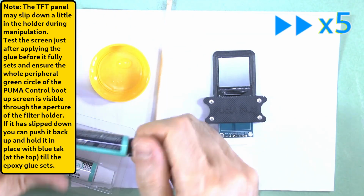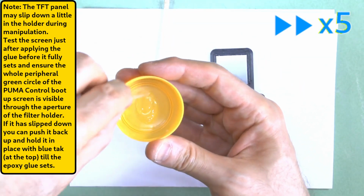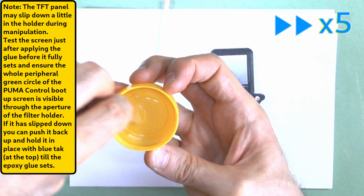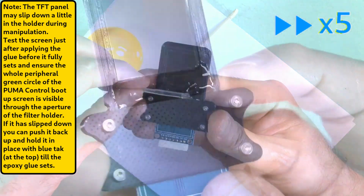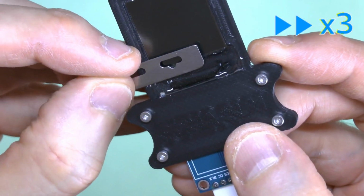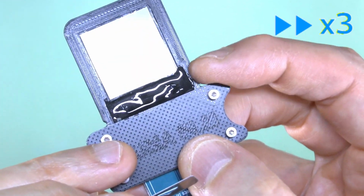Now that it is fully assembled and working, disconnect the power and further strengthen the fragile thin glass connector by putting a second wave of epoxy in the recess around and over the thin glass extension to strengthen it. This time you must glue right to and over the sides of the glass screen and contact the plastic of the handle with the glue to prevent the TFT screen from slipping during use.